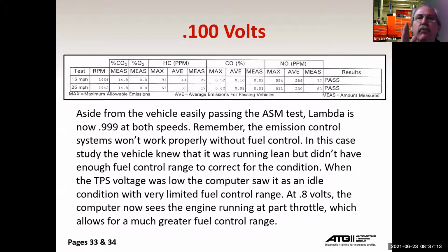But by applying what we talked about in this class, can the computer see what's going on? Is the O2 sensor working correctly? If it's working correctly and the computer is ignoring it, why? Let's look at, are we in closed loop for one? Then look at sensor priority. Why would the computer choose to ignore it? That's what led me to the answer. It wasn't all my years of experience or anything else, because I'd never seen this before. It was asking the right questions.